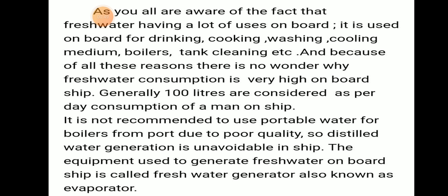It is not recommended to use potable water from port for boilers due to poor quality. So distilled water generation is unavoidable on ship. The equipment used to generate fresh water on board ship is called a freshwater generator. It can also be called an evaporator.